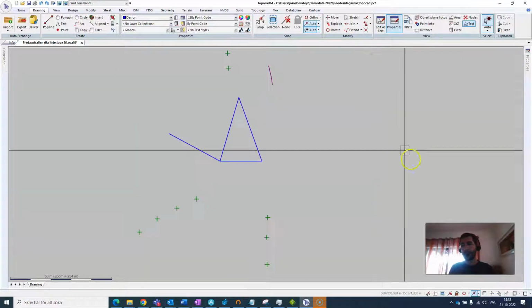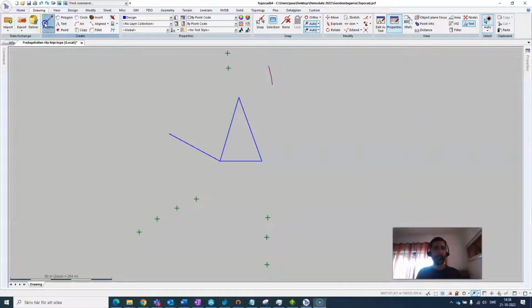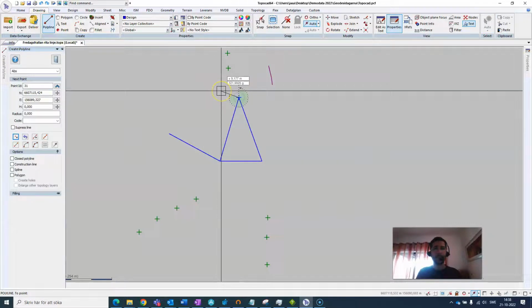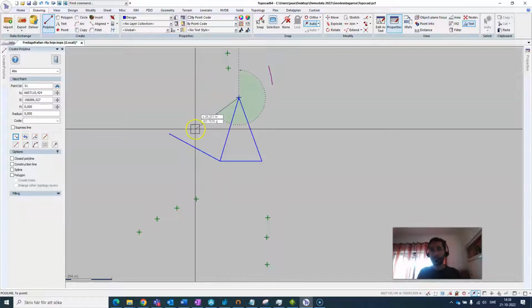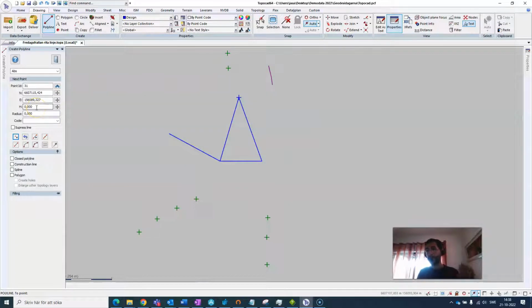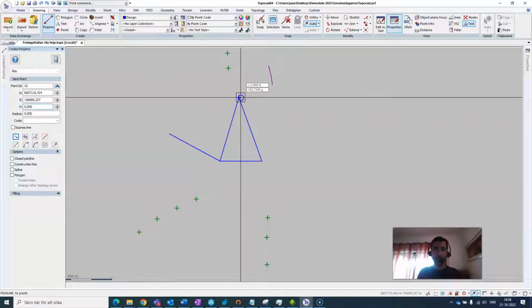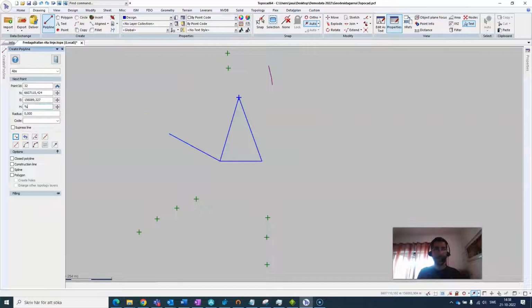And something to be aware of here is that the first point has to be a height and cannot be a slope. So we need to have a starting height. So in this situation, oh yeah, now I already clicked it. But if I'm already here, it will not allow me to input a percentage sign before I click on the first point.